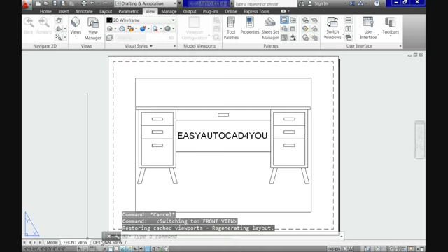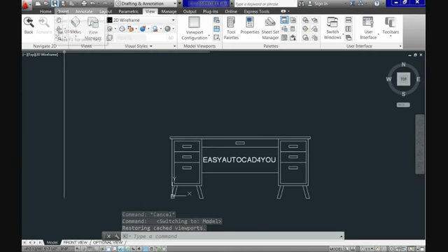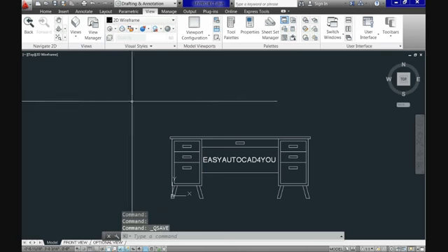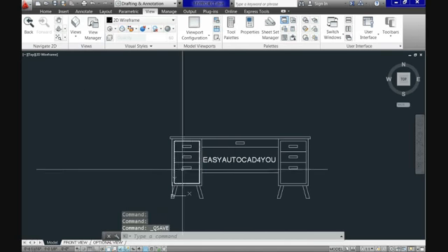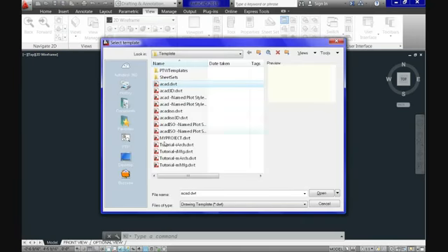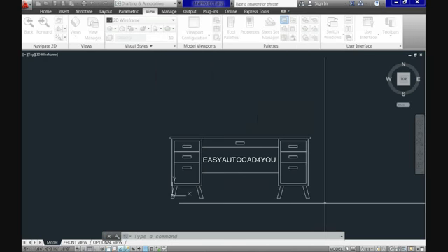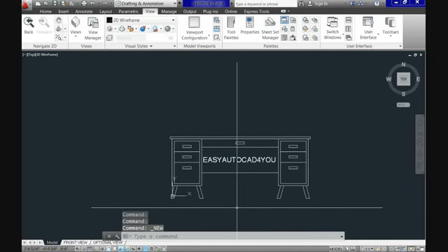After you quick save, because we are saving a DWT or a template, everything you did there is being pre-saved. It's already saved. You can open it and have it ready. If now you go here and instead of DWG you reference the DWT or a template, go to my project DWT and it's there. You see there the preview, and you see everything has been saved.